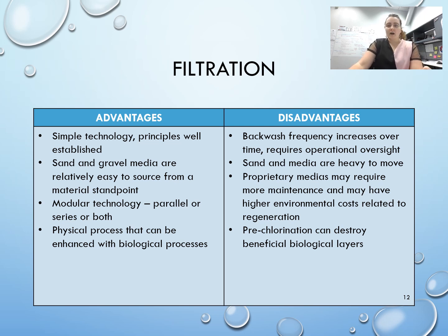Some disadvantages: our backwash frequency generally increases over time, and it requires operational oversight. So backwashing is something that we have to watch very carefully because the effectiveness of it over time decreases. Sand and media like gravel are normally heavy to move around, so when you actually have to replace these filters, it is a lot of manpower and a lot of effort. If you're using something like a proprietary media made by a company, it may require more maintenance and have higher environmental cost because you have to regenerate the media. And we can talk about that more in class if you have specific questions.